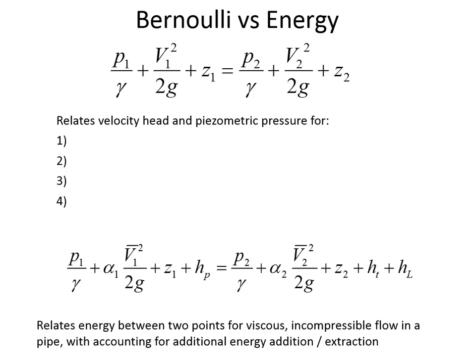That's not much of a correction factor, is it? We're just adding an extra 5% of kinetic energy into the velocity head term because using the average velocity sort of undercounts how much energy there really is. Sometimes people don't even bother including alpha. So sometimes, in a certain problem, I may say, well, let's just assume alpha is 1.0.